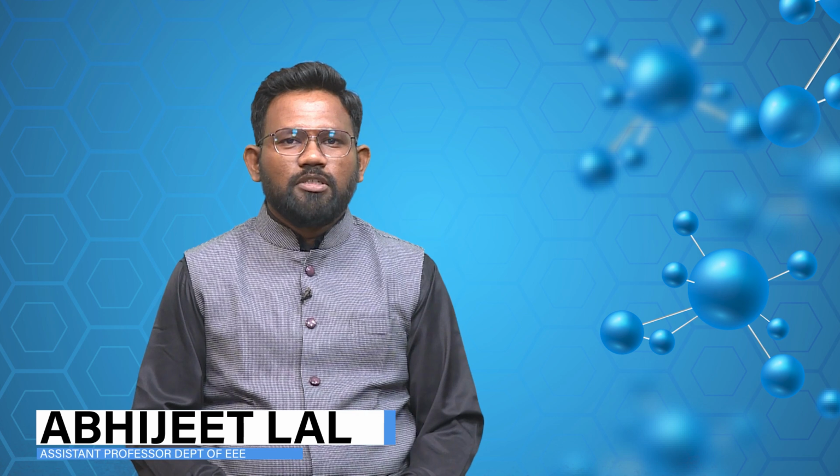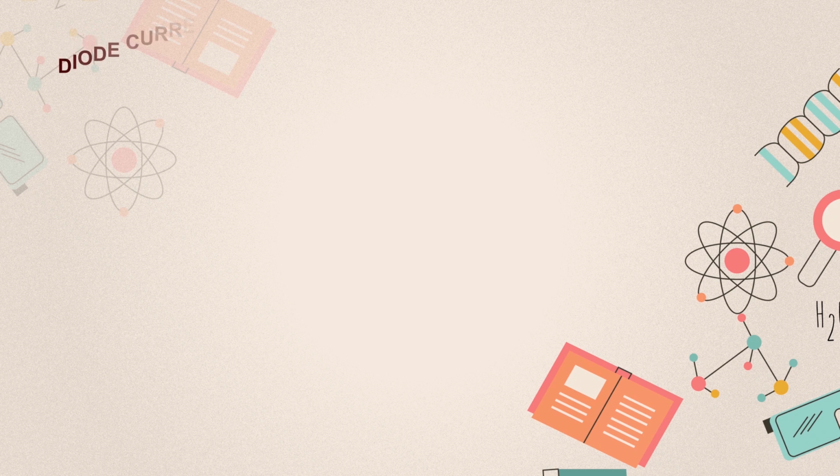Hello everyone. Today we are going to study about the diode current equation. As we have studied about the VI characteristics of a diode, in that characteristic we have seen two regions, that is the forward bias region and the reverse bias region, and there we have seen the characteristics between V and I. In the forward bias region the characteristic was exponential, and in the reverse bias region the characteristic was linear. So, we have to see the mathematical aspect of that also. That is defined by the diode current equation.